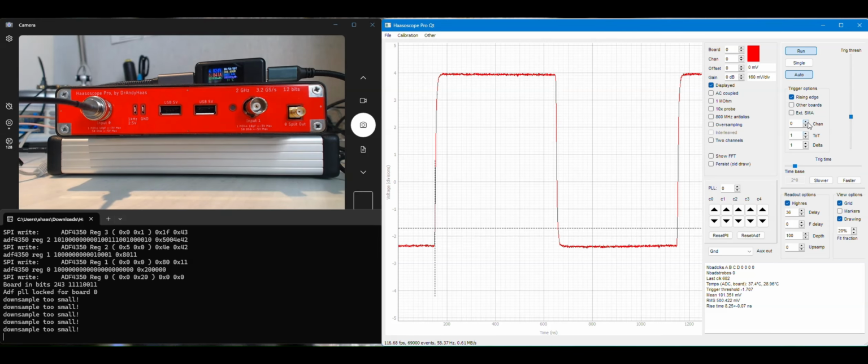It's actually a little more complicated than that. There's this time over threshold and delta trigger quantities, which we can adjust. Time over threshold says I need the trigger to go over this threshold and stay over this threshold for a certain number of samples. So you can adjust that, if you don't want to trigger on a really quick noise spike, but you want to trigger on just samples that stay high for a while.